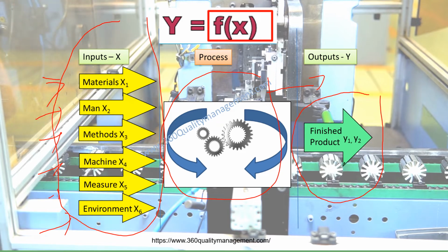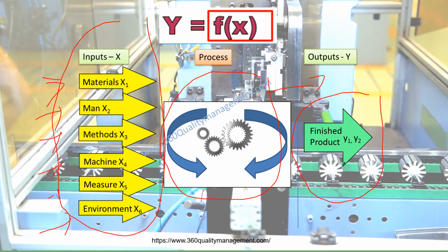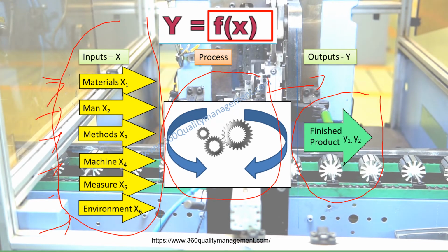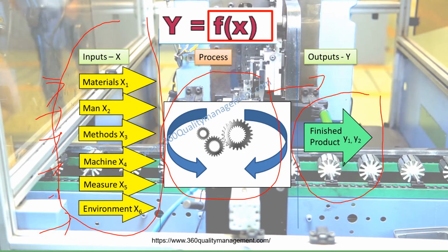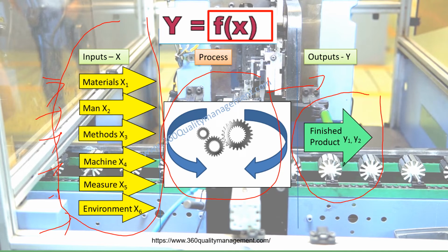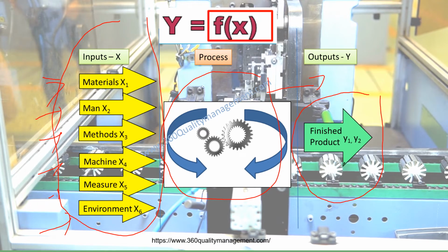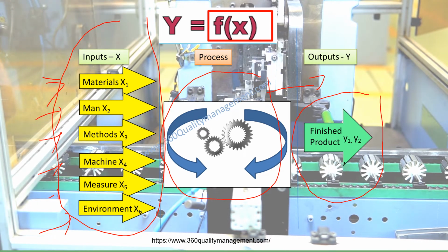The Pareto chart could be collecting the failure symptom, which is also related to process output Y. The histogram is plotting the process output into a distribution chart. Stratification is plotting process output Y from various sources such as different machines, different manufacturing lines, or different suppliers.